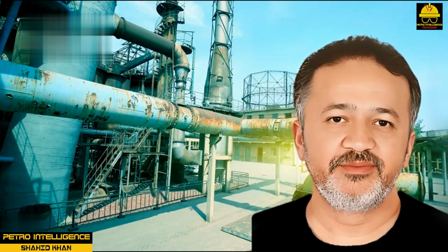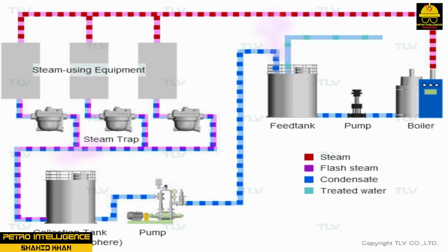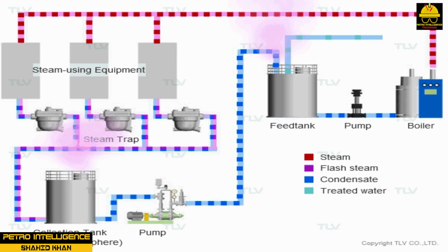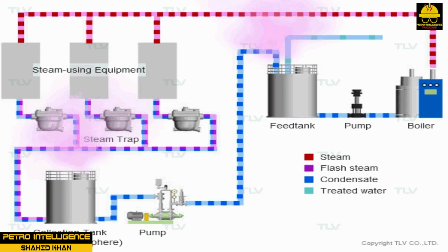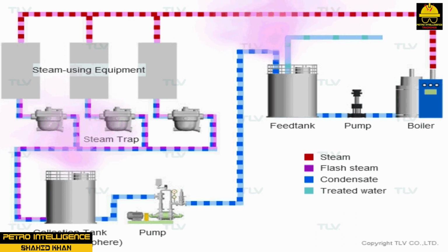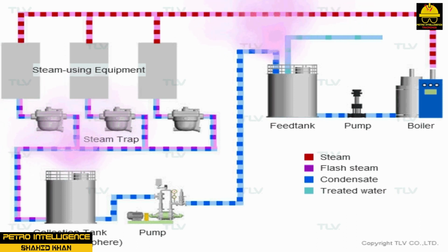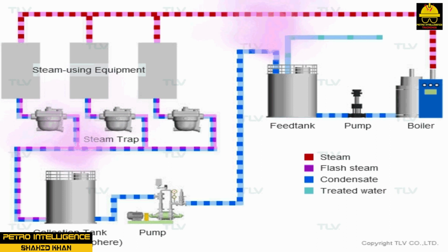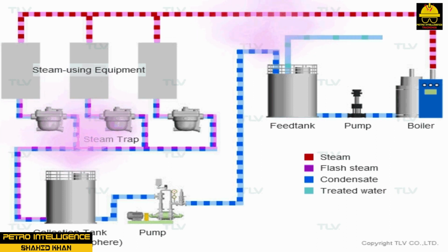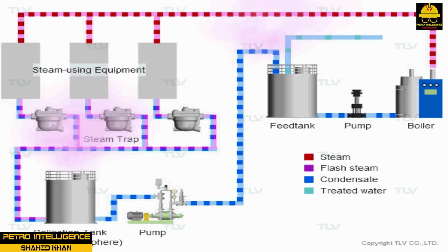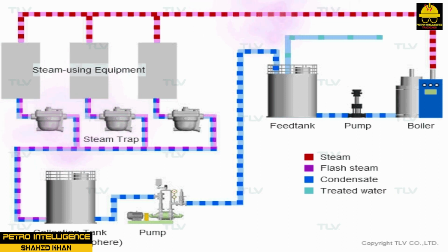Condensate recovery. The condensate recovery system is separated into clean and suspect, dirty, condensate sections. Clean condensate is routed to the deaerator. Suspect condensate is collected from steam users where the process side pressure is higher than the steam pressure. This condensate is considered to be suspect because a mechanical failure, such as tube leakage or failure, could cause contamination, and the reuse of contaminated condensate could seriously damage the steam generators and turbines.